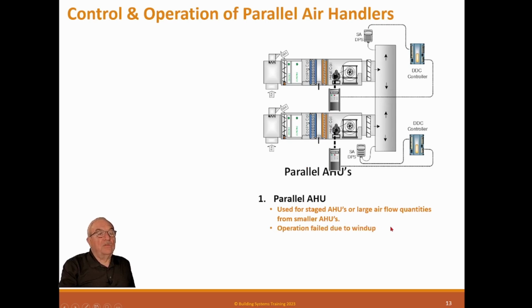Operation failed. This was the first job I ever did like this. I thought, well, this was cool, but operation failed due to windup. Now, what windup is, when you have some sensor variability, let me just go through this. If you have this situation with these 2 pressure sensors running these 2 fans, if this system is 1 second slower than this system, then when you come back the next day, this won't be doing the full load and this one will be doing 0 load.